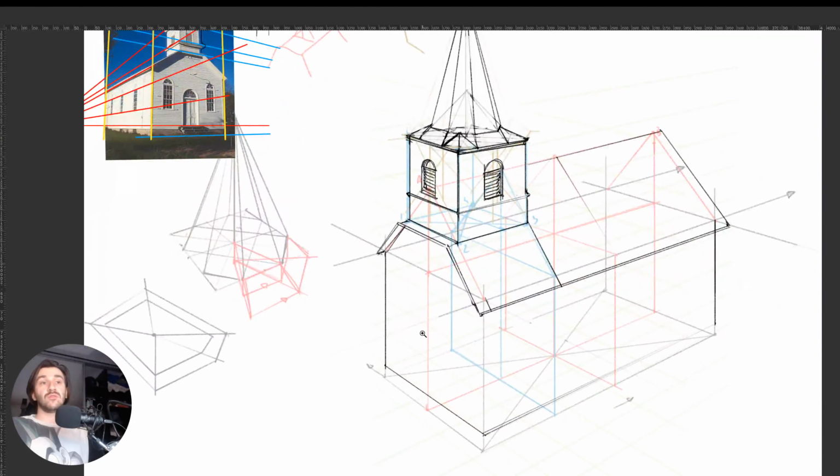And adding windows to the front and doors is pretty much exactly the same. If you want to do it in a little bit quicker manner, you can always, for example, use the symmetry tool. So look, this is a really cool thing, especially for Photoshop users to be aware of, because as far as I know, still quite a lot of folks are not aware of those types of tools. So at the top there is this butterfly icon, and in here you can simply draw a window in symmetry.